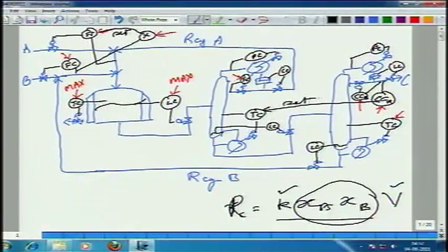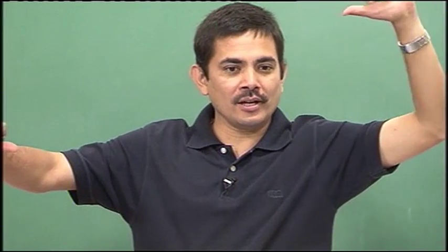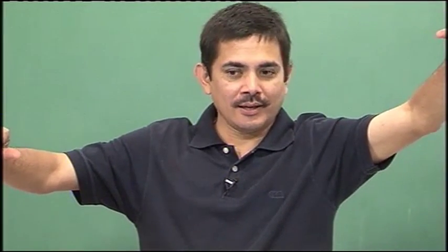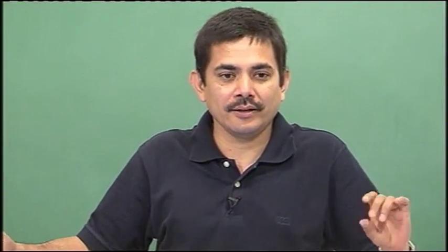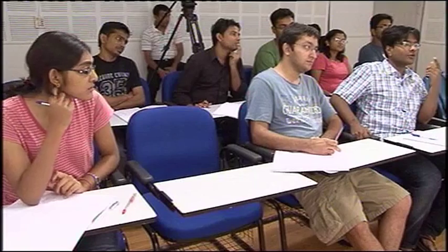So, but then eventually XC will increase. No, it will not increase eventually. This is what needs to be understood. So, if generation rate is increasing, then XC should also then increase, the amount of C should also increase. It will increase, but if you look at this steady state versus this steady state, where total A and total B was small, this steady state total A and total B to the reactor is larger, XC would have gone down, guaranteed.